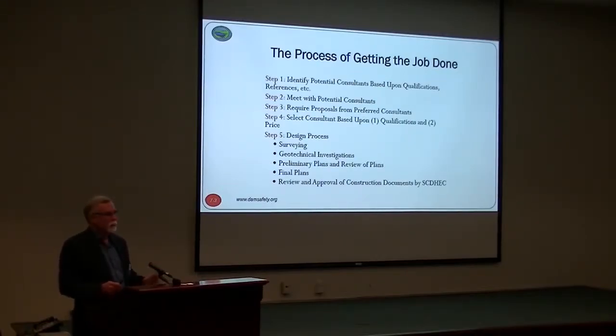So when the contractor is building the project, we're doing material testing and making sure the contractor builds it correctly. At the end of the job, a set of as-built drawings is given back to you for your record, because very seldom is the dam built 100% like the original drawing. There are always little things that are changed, typically during the construction process.